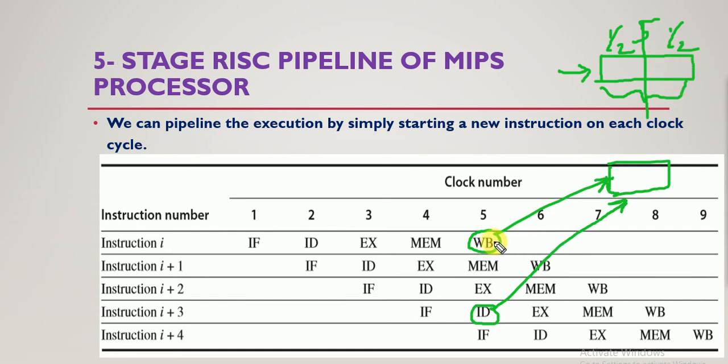So this write back will have priority if these two operations arrive at the same time. A write back in the first half of the same cycle, this writing will happen, and in the second half, instruction decode. So here write back first will happen, then in the second half of the cycle instruction decode, that is reading, will happen.